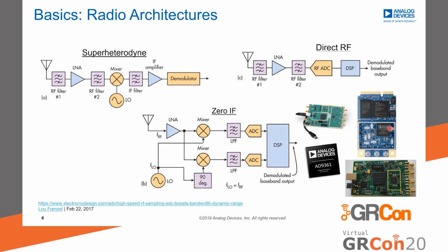The new N series devices have devices like these, like anything that's based off of the 9361 or 71 or any transceivers from ADI all use this zero-IF architecture. With zero-IF, the big advantage is it's highly integrated, so you don't need a lot of components around, and it's very flexible, so you can have large LO ranges, large bandwidth changes. But the consequences are that you need algorithms to handle things like mixing products or DC components that are involved. And this is why zero-IF has only been around for a couple of decades compared to superhet.